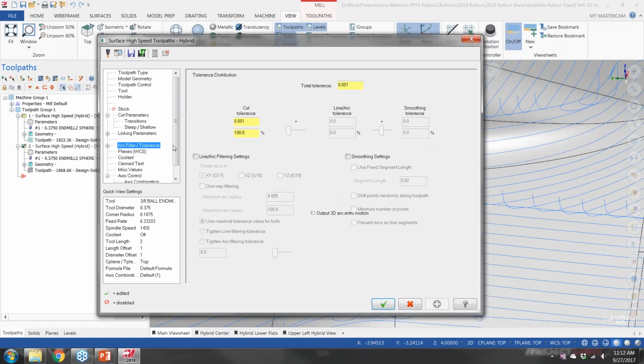And if you guys don't know, the arc filter page would be down here. If you do turn that smoothing on and realize the program got a lot longer, say there's a lot of scallop motion in that particular hybrid toolpath, always be mindful that you can set your total tolerance and turn on filtering, depending on what your tolerance of a given part was. I had a lot of questions on this at the in-person rollouts, but the easiest way to explain this is I would probably set this to at or below what my tolerance is for the part.